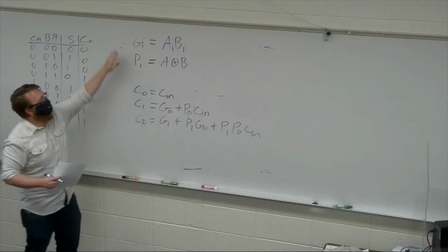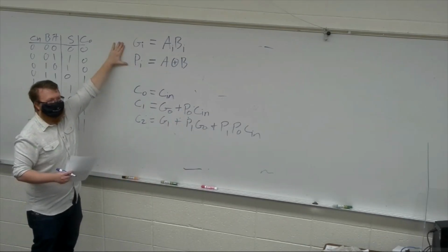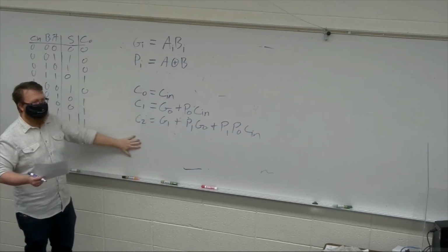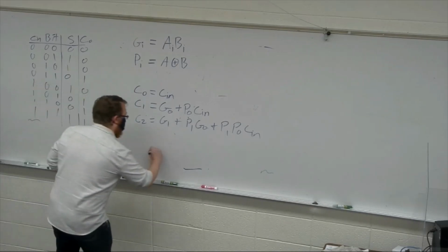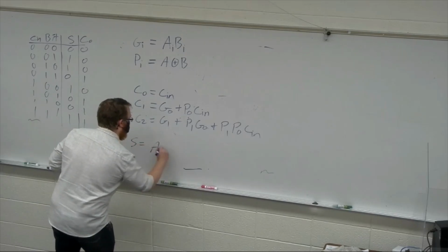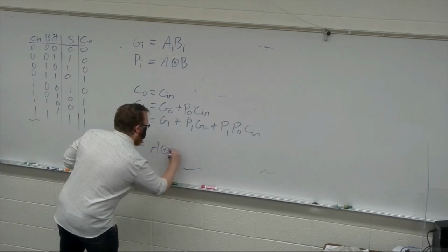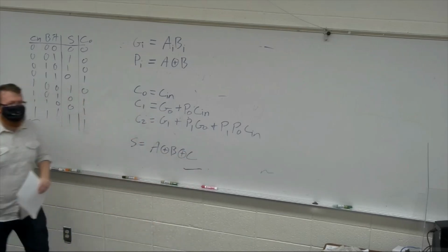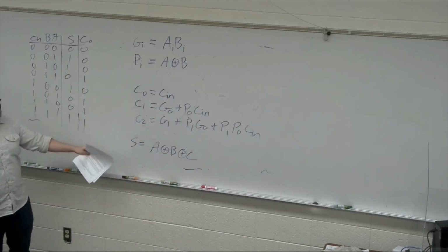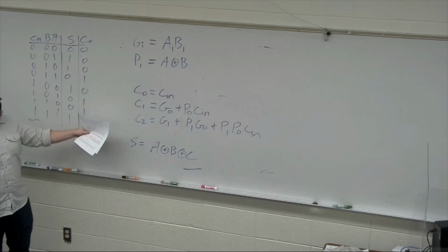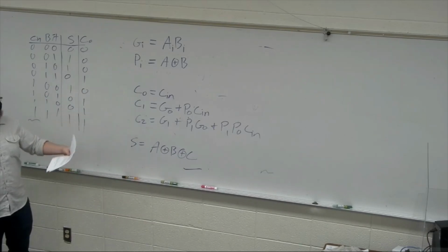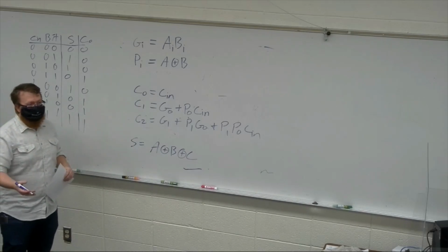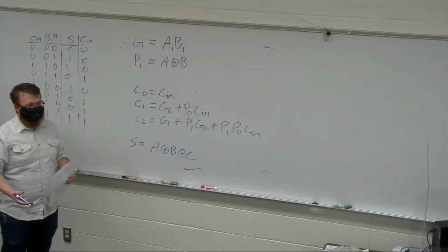So we've got one gate delay, two gate delays, and then the final stage, one gate delay. So in just 4 gate delays, we're done, regardless of how many bits we have. So this has a benefit of being very fast, but very large.